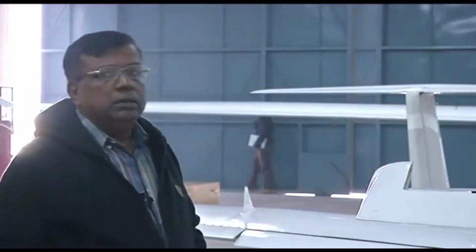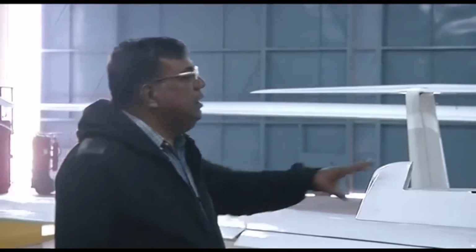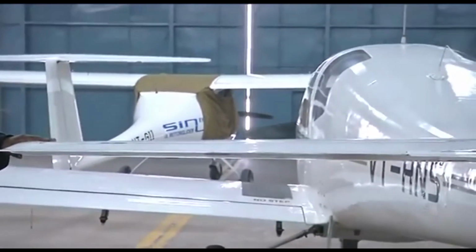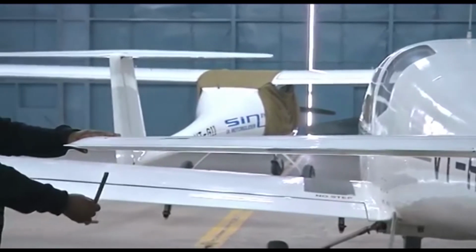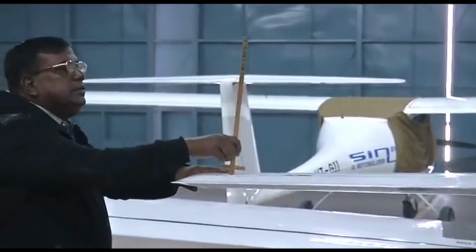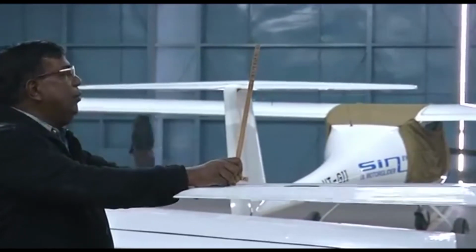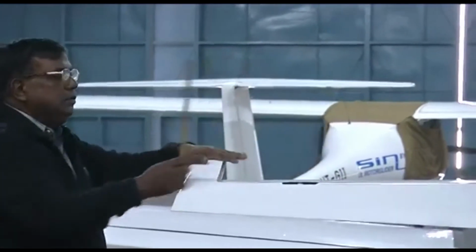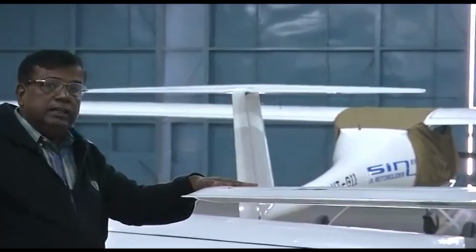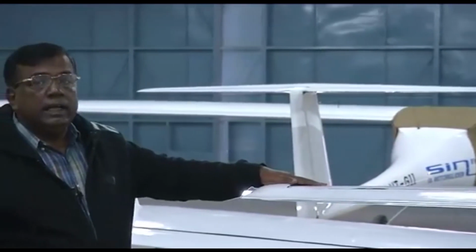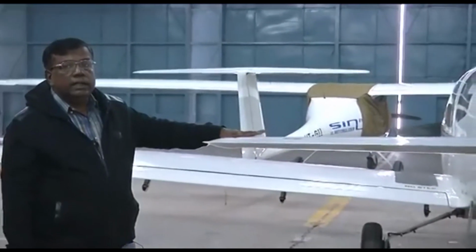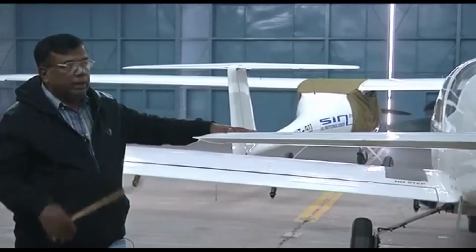You know by now longitudinal stability, and the understanding was that if this airplane is flying, this is the tail plane, and if there is any angle of attack disturbance coming like this, a positive angle, then it will generate a lift, and this lift will give a nose down moment about the center of gravity. So, we say for a positive alpha, the tail is producing a nose down moment which is negative, and we say Cm alpha is negative. So, the contribution of the tail is towards making the aircraft statically stable in the longitudinal plane, right.